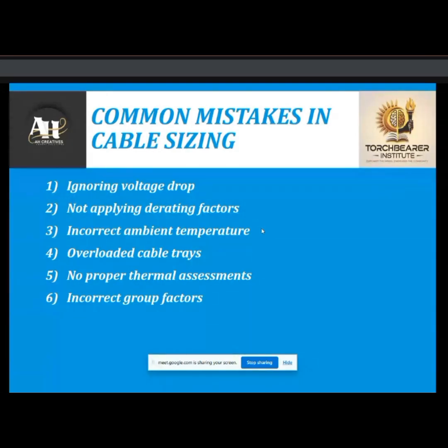The IEC standard says that the cable tray should have free space while installing the cables, like 30 to 40% of the cable tray should be spare. But many vendors and EPC contractors, who have cost limitations, will overload the cable tray. Due to that, the cables will burn due to the heating effects of the other cables.